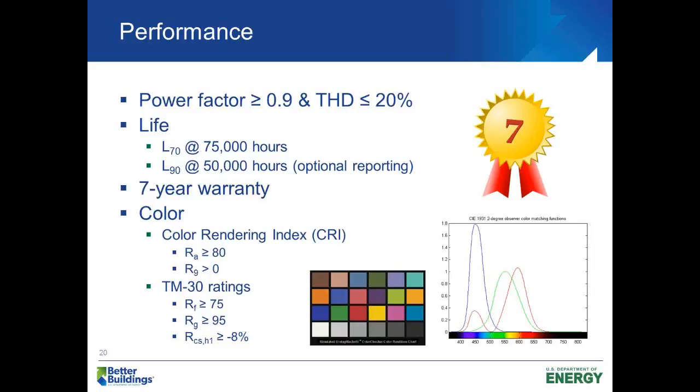I'd also like to clarify that some of these longer life requirements are not entirely being driven by us as a benchmark. We're hearing often from end users the desire for long life products. So this is keeping it consistent with what we're seeing from end users who are ultimately going to be buying the product. They're asking for these long life requirements. In particular, that 6,000 hour, yes. If you have limitations on 6,000 hour chip testing, that will constrain you. But you're right. As you have a higher number of hours that you tested your chip, the better your extrapolation and the better your TM21 method will be.